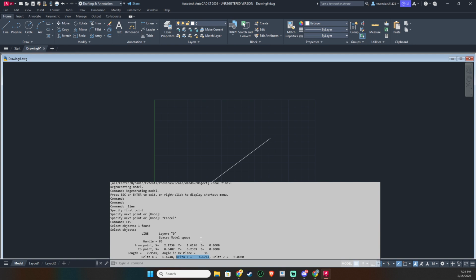One of the nice things about using list is that it respects your drawing's units automatically. Whether you're working in feet, meters or millimeters, the percentage slope remains consistent because it's a ratio. If the numbers don't match what you expect, double check that you selected the right object and that the endpoints are in the correct locations.